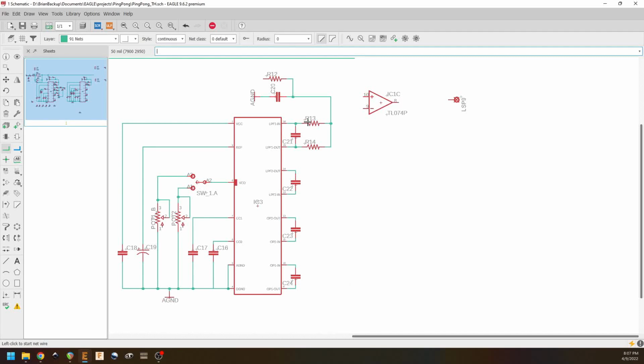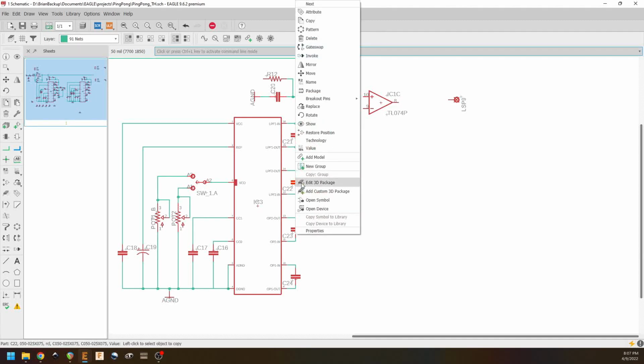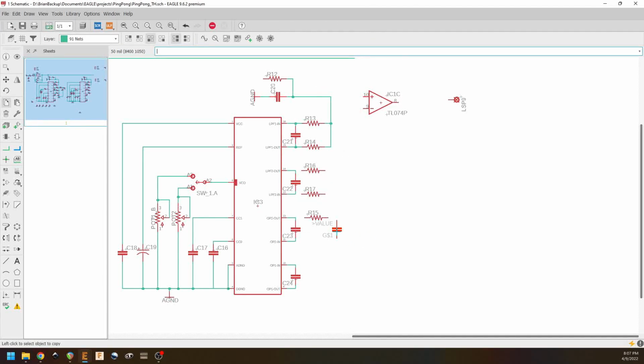So now we need to create our multi-feedback arrangement off the output of this op amp. So we're going to go like that. We're going to need a resistor there and a resistor there. We're going to need a capacitor to ground. And then let's connect this up so that we've got our multi-feedback filter all squared away.